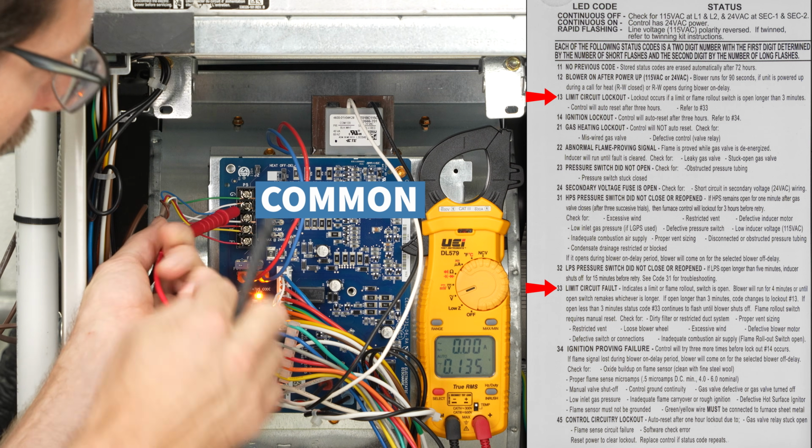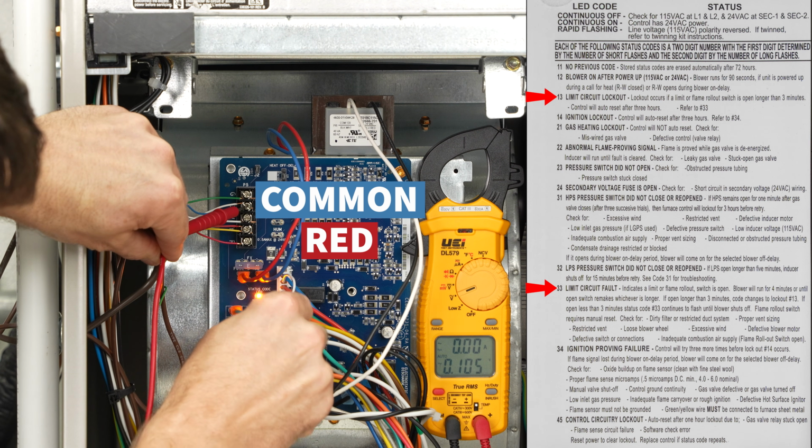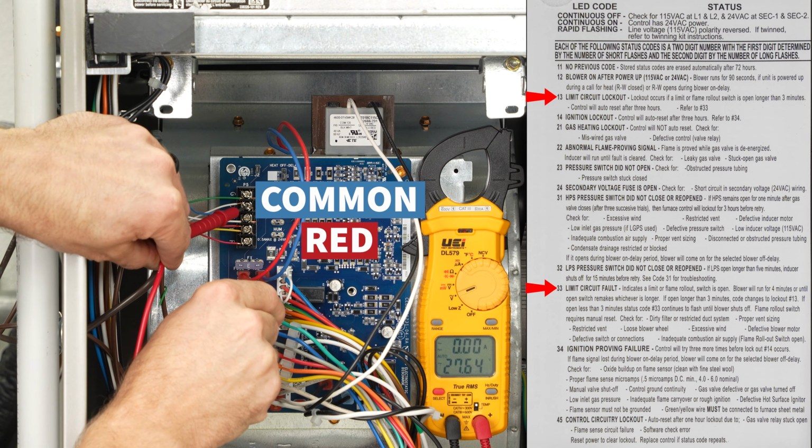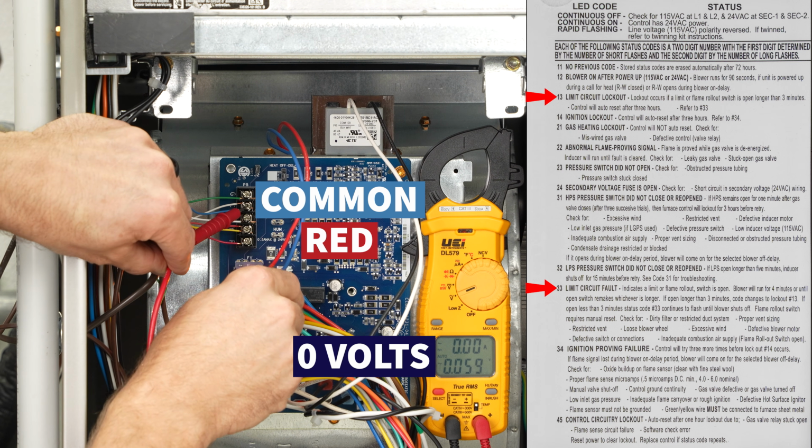we can just check from the common, so make sure you can see that, to this red wire right here, and you can see we have 27 volts present there, and we have 0 voltage right here.